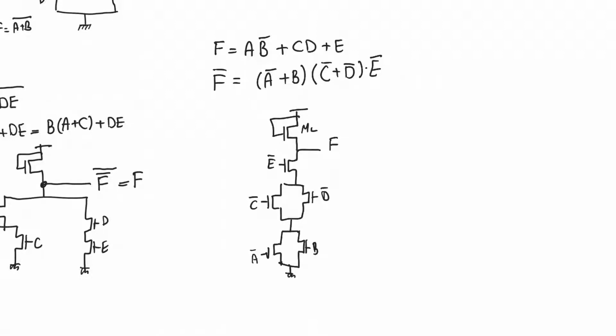The question is now, what is the number of transistors in this logic gate? And this question depends on one thing that should be given when we are given the problem, which is, are the input variables and their complements available without additional inverters? If the answer is yes, then you will only count the transistors in the main gate. If the logic inputs are not available in true and complement form without additional inverters, then the fact that you are using E bar, for example, means that you have to use an inverter to get E bar. And you have to count the transistors in these inverters.